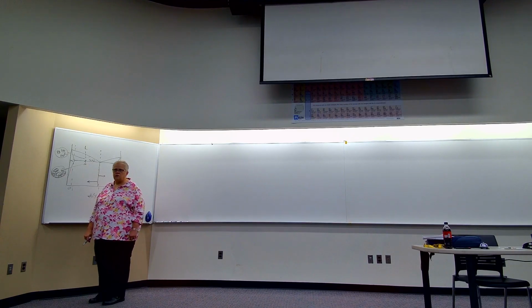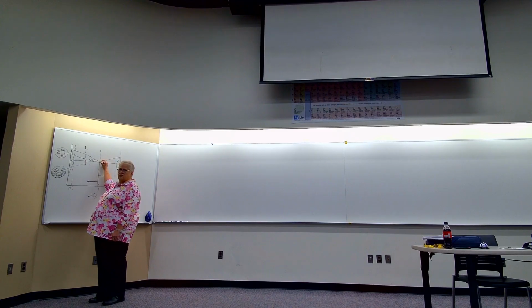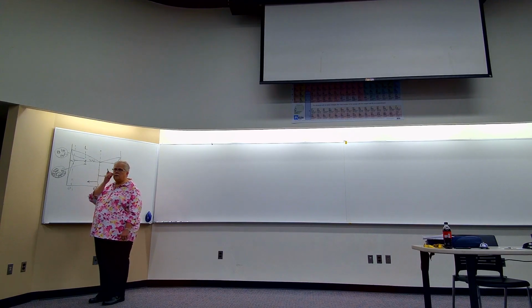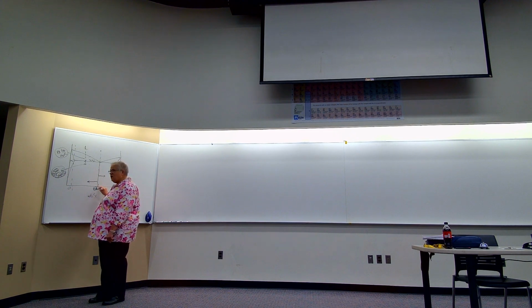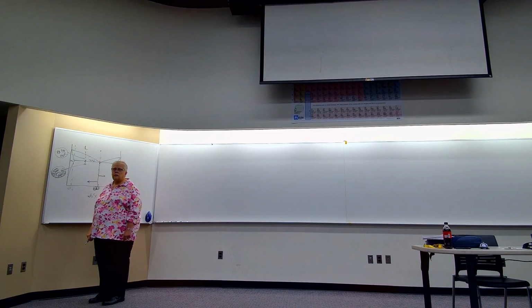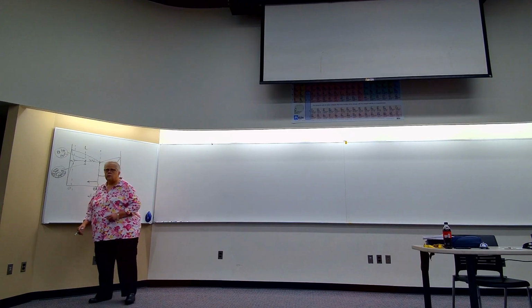It might seem obvious, which holds you back. It might seem like I have absolutely no idea, which holds you back. If I'm here, what's the composition of my eutectic? Whatever this is. No matter where I am, that's the composition of the eutectic. No matter where I am, the composition of eutectic is whatever the composition is of eutectic when it forms. Now, the eutectic might have slightly different amounts of alpha and beta, but its overall composition is constant. Okay. Gave you more than you asked for.